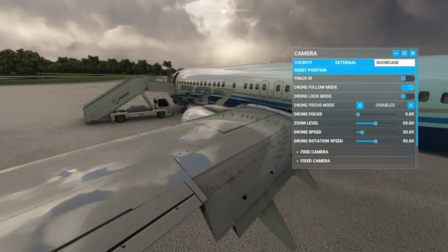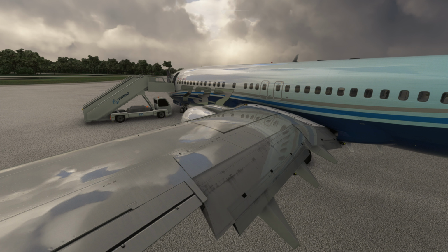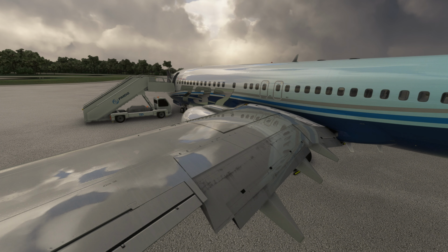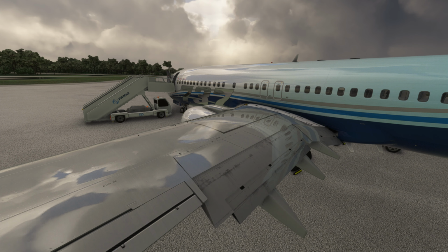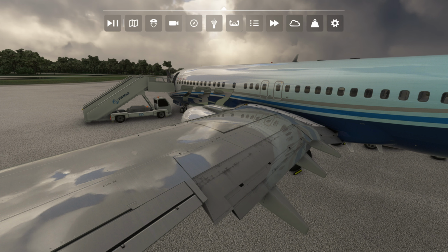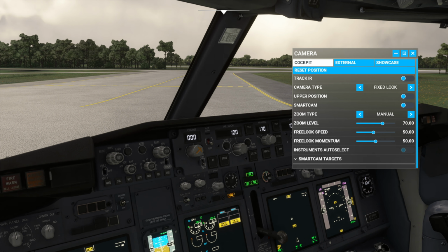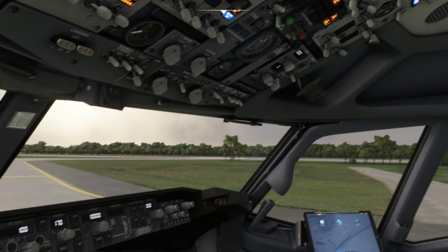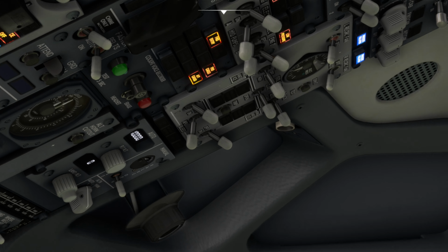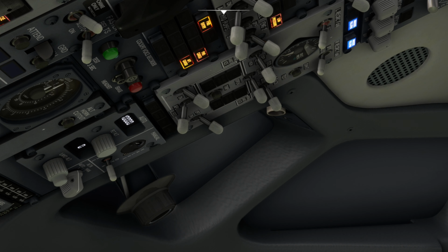You'll hear the hydraulic motors running here. So when you have hydraulic pressure on the aircraft, it means that you have the full ability to actuate the slats, flaps, and spoilers as you would need for a nominal landing configuration with or without the landing gear. As the flaps come up, we also have our pneumatic system running, the APU obviously providing pressurization and climate control for the passenger cabin as well as the cockpit.